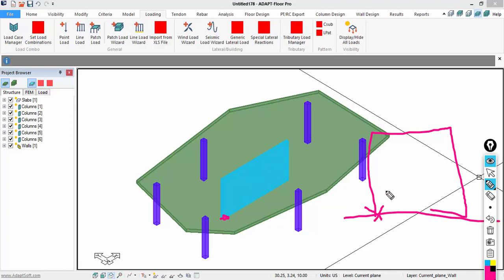The direction to the start of the opening, for example, if this is our opening, this is going to be the S direction. This is going to be the R direction, and that's the current setting. When this is released, this will actually become R and this will become Z. So right now we just have a couple of placeholders for the reference point. So we define the reference point of the opening, and then we define the width and the height of the opening. We'll do that for this wall.